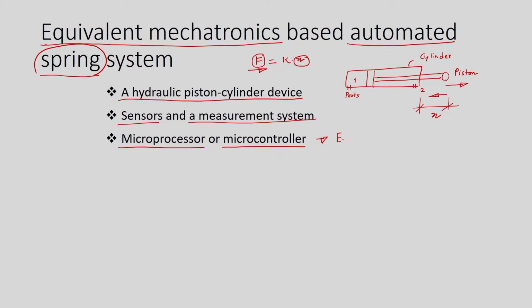So, we often use the term embedded systems. The meaning of embedded system is that the microcontroller or microprocessor based system is integrated into the mechanical system and the end user is not allowed to program it. A simple example is a washing machine. We cannot reprogram or edit the program of the washing machine. Whatever the designer or manufacturer has given to us, we have to use the same program or the same mode of operation.